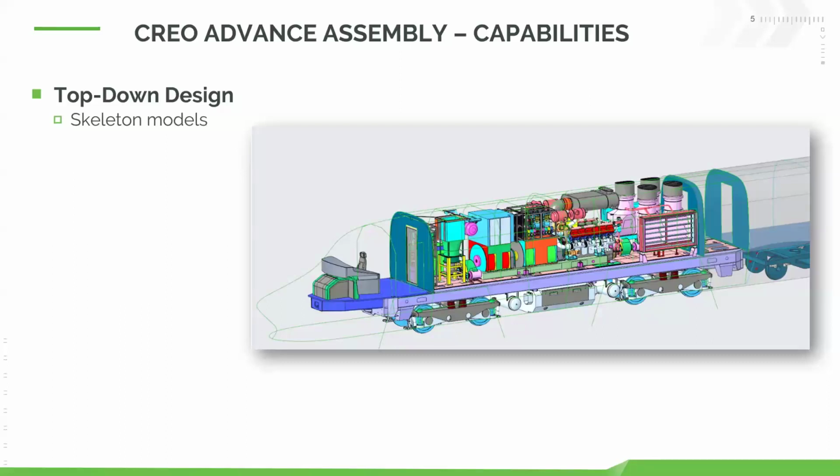And that's really working with the idea, first and foremost, of skeleton models. You'll see this whenever I go through the demonstration, but we're essentially laying out the framework for which areas of the assembly that we're working on, gives us the ability to share and work with only the areas that we're concerned with. We also have a reference viewer in this tool as well for viewing and managing all the different references and dependencies between the different parts, assemblies, sub-assemblies.